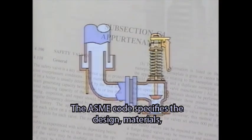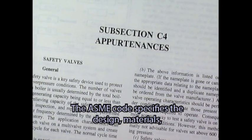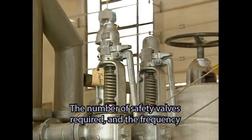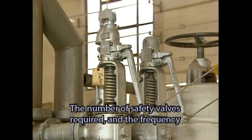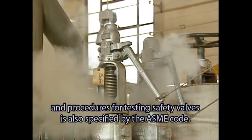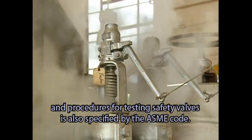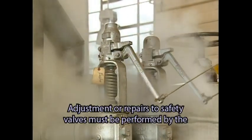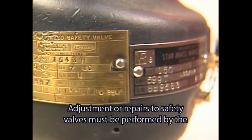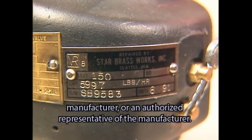The ASME code specifies the design, materials, and construction of safety valves, the number of safety valves required, and the frequency and procedures for testing safety valves is also specified by the ASME code. Adjustment or repairs to safety valves must be performed by the manufacturer or an authorized representative of the manufacturer.